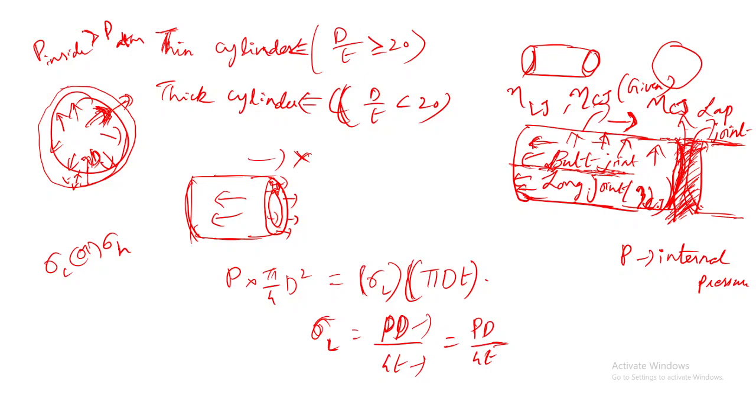Circumferential joint, yes, because that is the thing which is holding towards the circumference, right? We are actually getting the required length by having the circumferential joints. So whether it should be multiplied by circumferential joint or divided by circumferential joint. If I am multiplying this by circumferential joint, then the value of longitudinal stress I will be getting is less. That means I am undermining the efficiency of circumferential joint. So I should divide this.